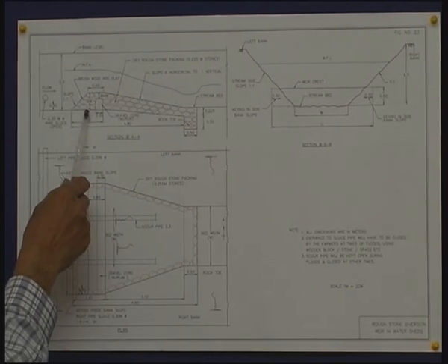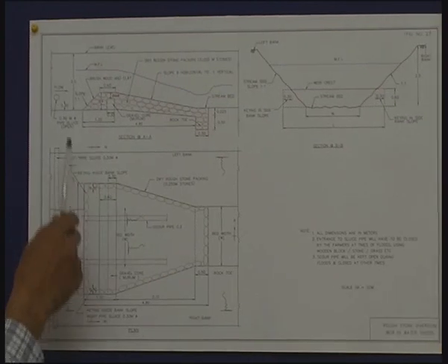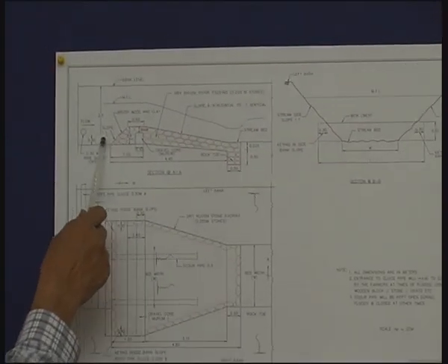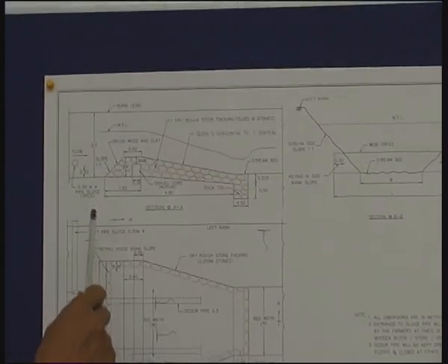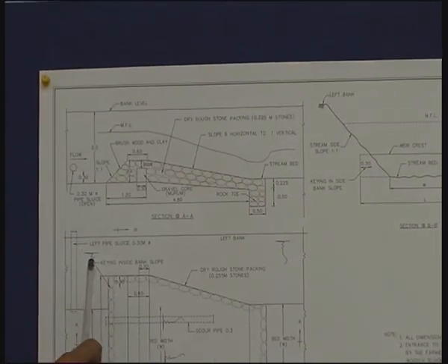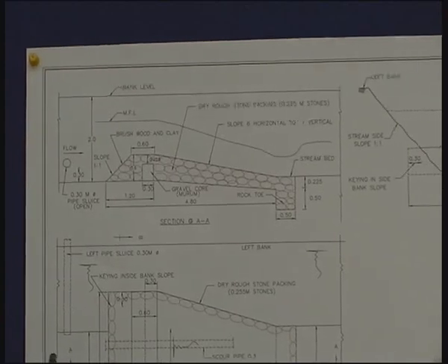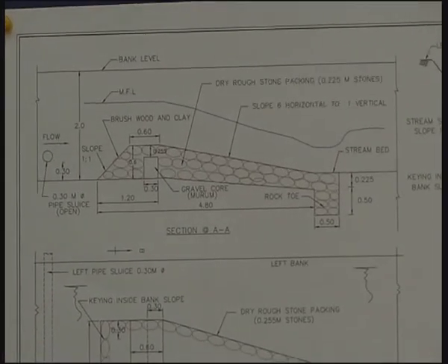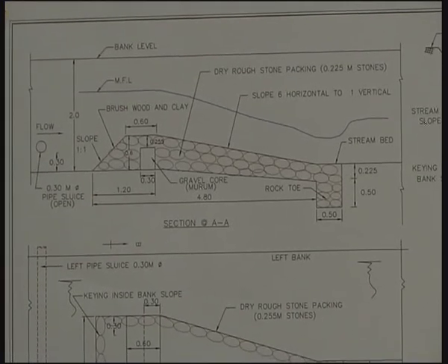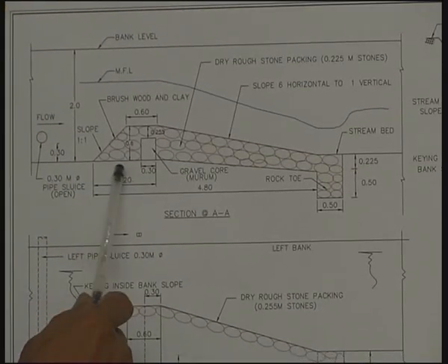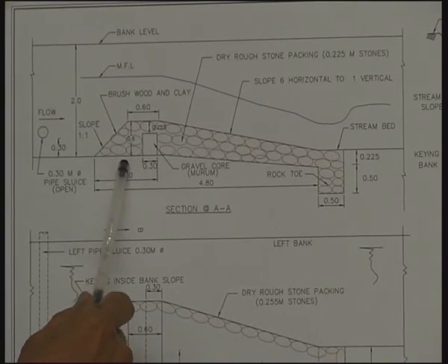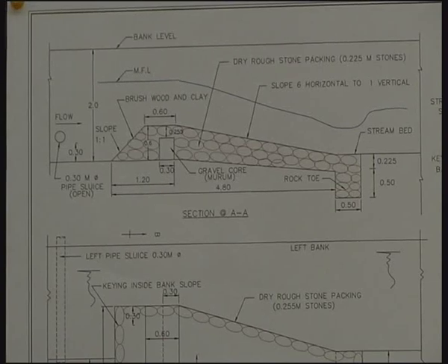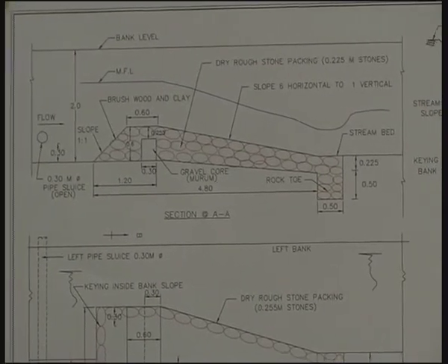As we see here, it is only 0.6 meter height. We do not require a very high obstruction because it is enough if 0.5 meter depth of water is diverted into the canals. The canals are going to be either 0.3 meter depth or 0.4 meter depth or 0.5 meter depth. So, this structure of 0.6 meter height would be able to divert a canal depth of 0.5 meters.